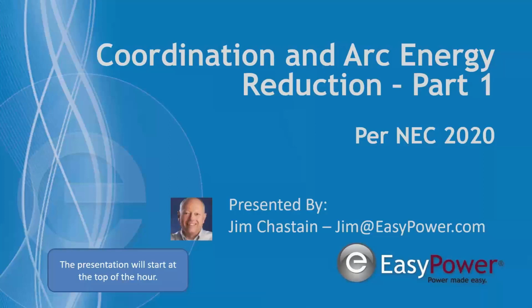The NEC makes it clear that new design and selective coordination is considered engineering level work and should be done and approved by professional engineers. An arc flash study is neither of these activities. It's a function of the arc flash study to verify the current standing of the equipment rating and incident energy levels to determine if a correction is called for. And so that's the focus of my presentation: how to use EasyPower tools to verify the current condition of the electrical system, and then how to produce the information needed to substantiate that fact.